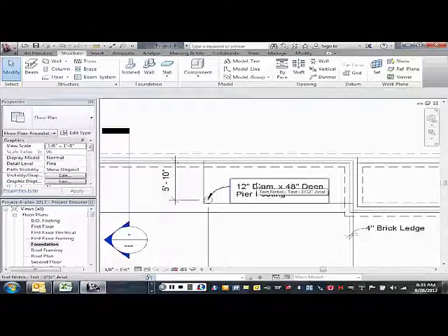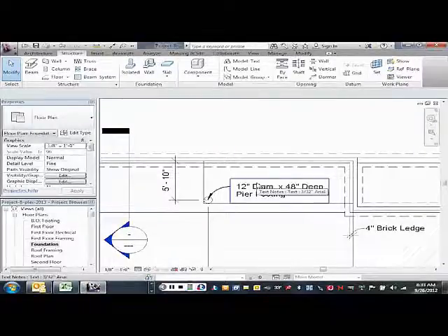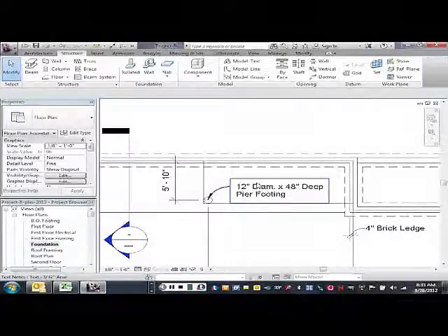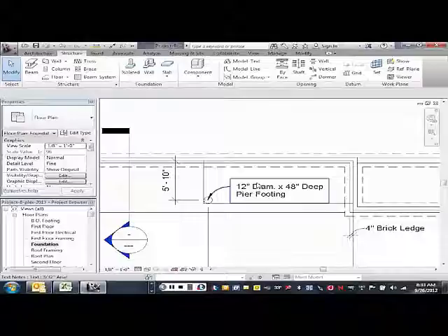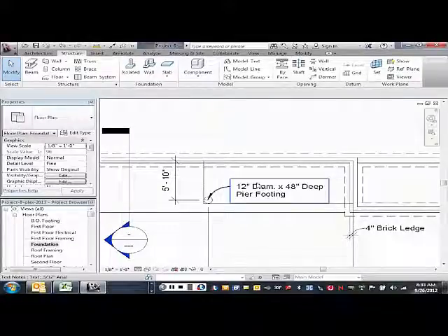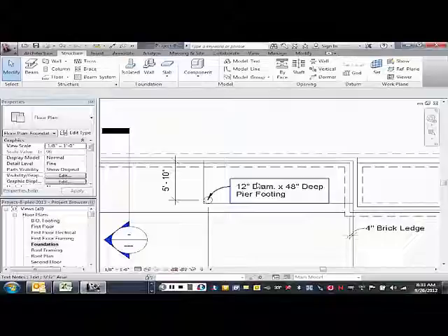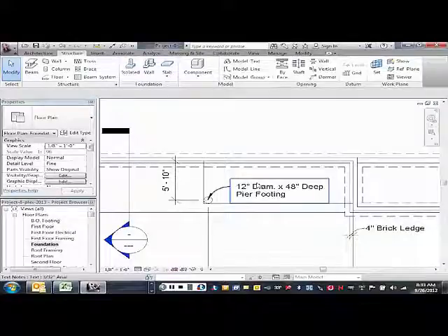Because the patio is sitting on the brick ledge, now what about the brick that are going down onto the brick ledge? Right. And this is a case where the patio could get poured and then the brick could come over and sit on top of the slab. Right, and as far as the detailing, we can do that when we do the cross section.